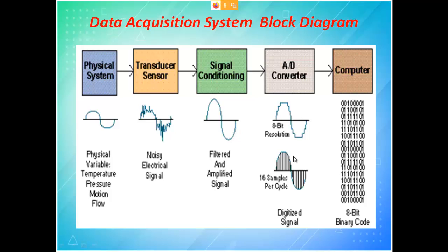Here comes your resolution. The higher the number of samples, the greater the resolution. For each and every step, you will have a digital output, and this entire digital output will represent this signal. A sine wave cannot be represented by a single value, so we have various digital values, and all of them together represent this sine wave. So now we have obtained the data.